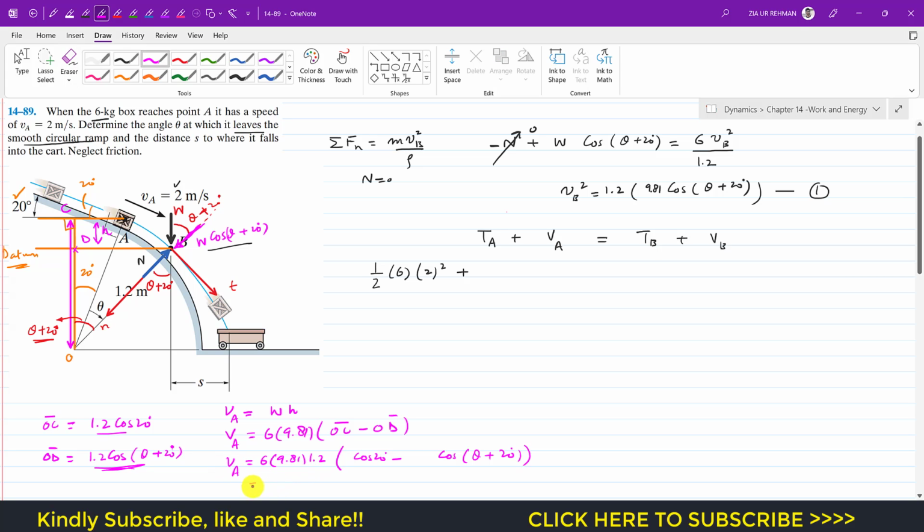So I can write this as 1.2 into 6 into 9.81 (cos of 20 degrees minus cos of theta plus 20 degrees). So this is the potential energy at A, and now I will write that here.